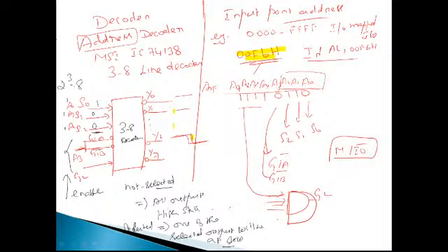What you do is that you can connect your M/IO bar like this. This inverter is required here because we want to have a logic 1 here. When an IO operation is coming, this will become 0, this will become 1. So this ensures that only for IO bus cycles, G2, the input of the 3 to 8 line decoder, will be enabled in concurrence with the other set of address lines, right?